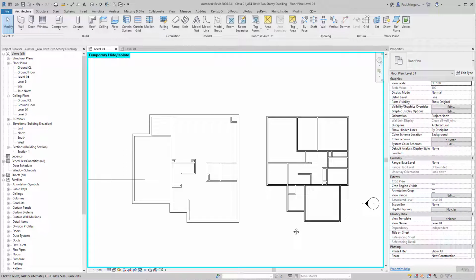We need to find some reference point that we can conjoin the two levels. Now, this is a little bit different to how we might design a building in Revit because essentially we've got the floor plans already, those reference floor plans. We've just drawn them both in two different locations and we're going to move them over the top of each other and then sort of connect them.